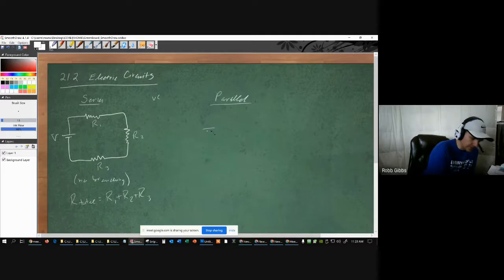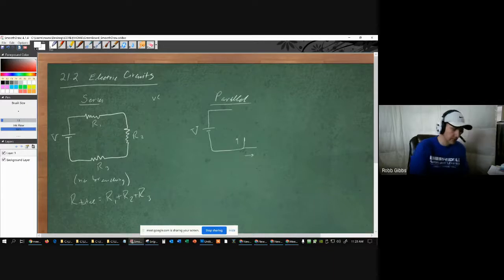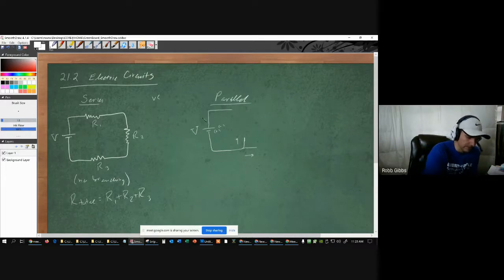That is different than a parallel circuit. In a parallel circuit, you have your power source, just like a series. Then you have a branching. So maybe right here would be a split, where some of the current can go here and some of the current can go there. Well, which direction is the current going? Again, current flow. So this is negative, or this is positive. Current flows in the opposite direction as electrons flow. Electrons are going to flow away from the negative toward the positive. So if electrons flow there, current's going to flow this way. So the current can move off into two branches here.